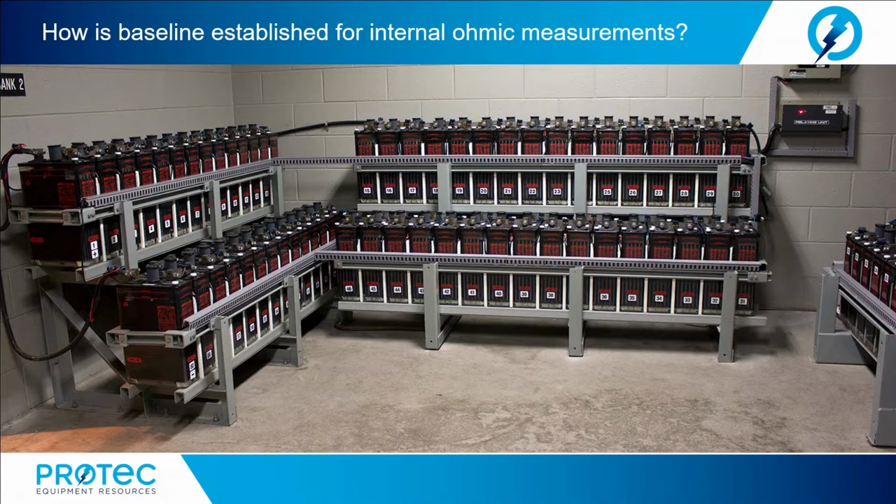Also, several of the battery manufacturers have libraries of baselines for their products that can be used to trend to. However, it is important that when using battery manufacturer supplied data, it is verified that the baseline readings to be used were taken with the same ohmic testing device that will be used for future measurements.